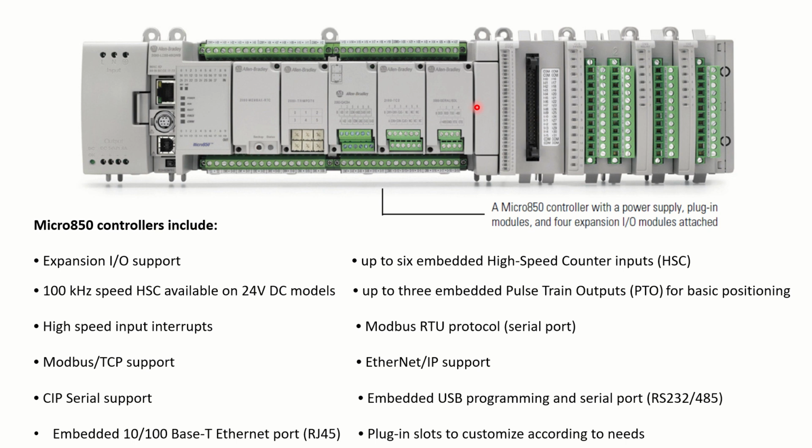Now many times nowadays, such type of PLC comes with the basic system, that is the power supply and the basic CPU, and that CPU itself contains some special functions like motion control. The Siemens Simatic S7-1200 can be further added with certain separate modules, but the CPU unit is inbuilt with a motion control input module. One of the output terminals has this PTO, that is pulse train output, which is not available in many versions of PLCs.